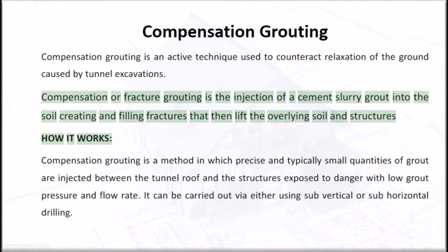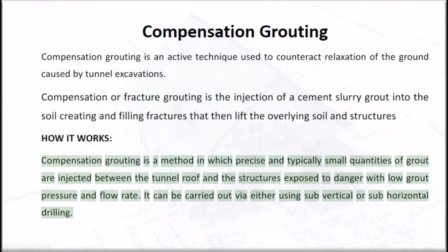How it works. Compensation grouting is a method in which precise and typically small quantities of grout are injected between the tunnel roof and the structures exposed to danger with low grout pressure and flow rate. It can be carried out using either sub-vertical or sub-horizontal drilling.